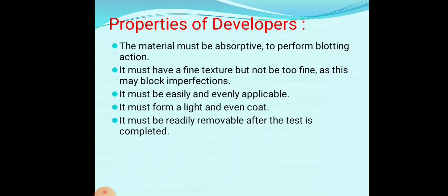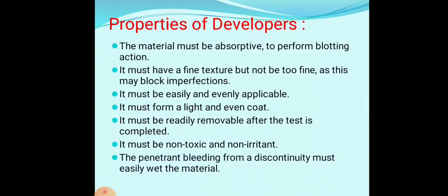It must be readily removable after the testing is completed, and it must be non-toxic and non-irritant. And the penetrant bleeding from a discontinuity must easily wet the material.